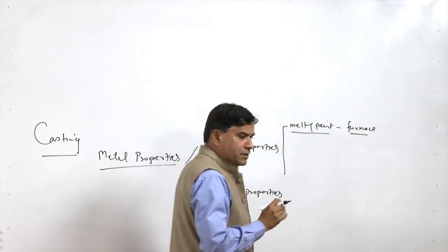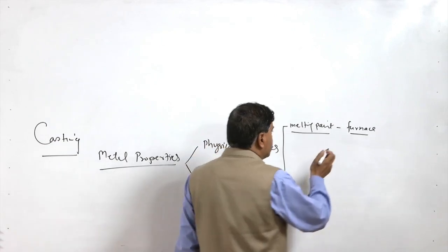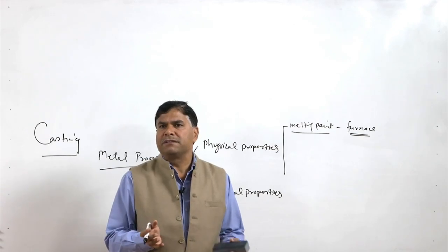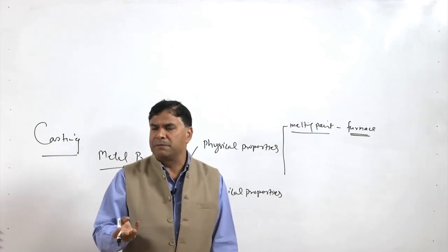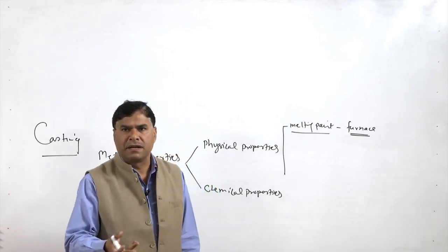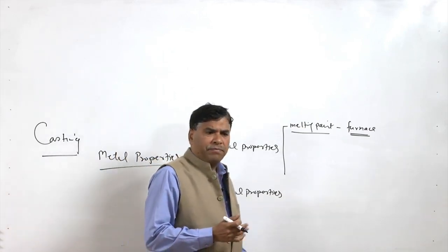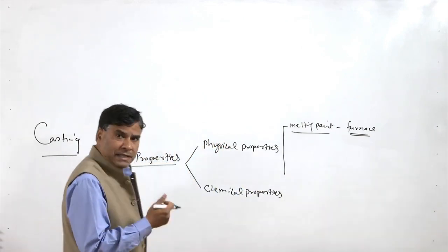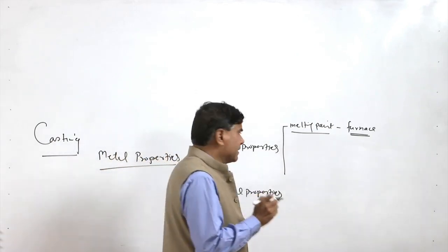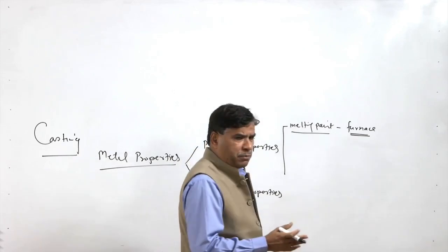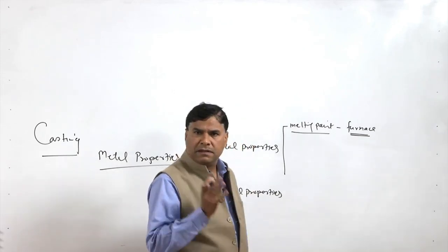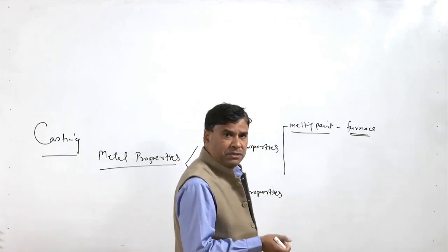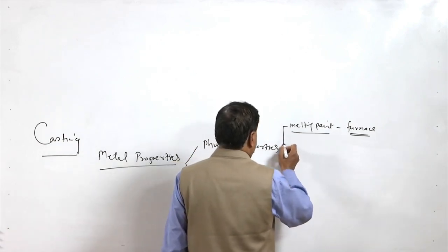For example, resistance heating furnaces can be used for melting low melting point metals like magnesium, zinc and aluminum, but arc furnaces are needed on the other hand for melting high temperature metals like steels and cast irons, although cast irons are of low melting point, like say 1050 to 1150 degrees centigrade. This is the kind of temperature which can be achieved using coal fired furnaces also.